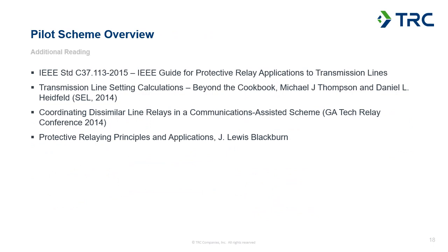So I've included some additional references on here. A lot of the figures that I used for this presentation I pulled right out of IEEE C37.113, which is the IEEE guide for protective relay applications to transmission lines. Anytime you're looking for any information or references on any kind of protection scheme, the IEEE standards are a great place to start.